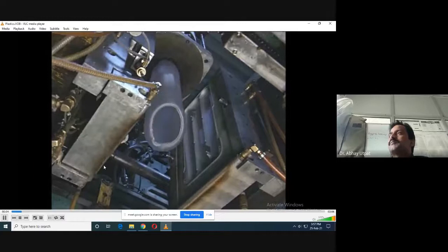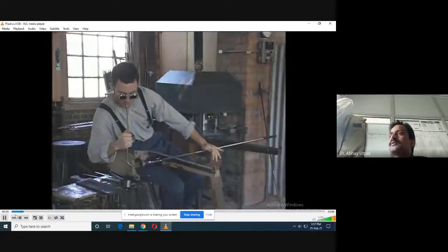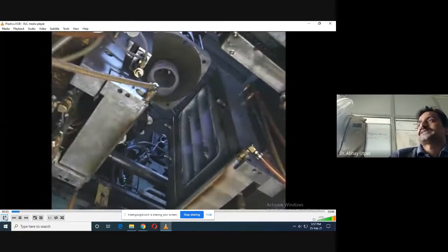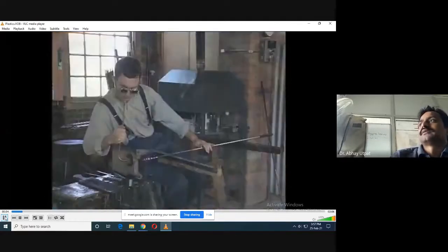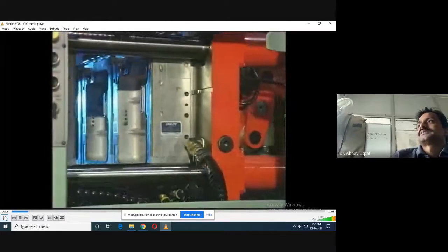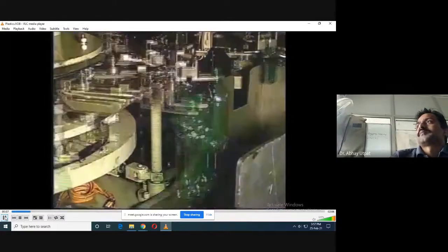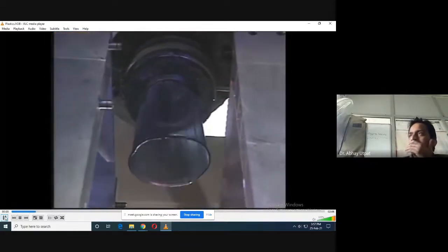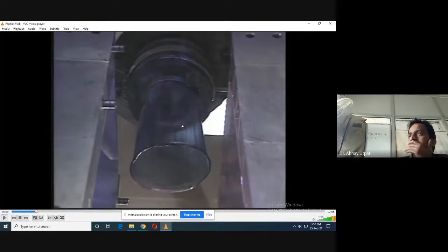See this extrusion blow. Once again I will show it. Please pay attention. Extrusion blow molding, how this product is produced. See, this parison is coming downside. Okay. This is a glass. See this. Bigger jars, bottles. See, this is called a parison, which is coming out by extrusion.